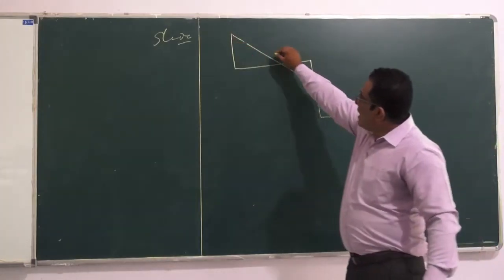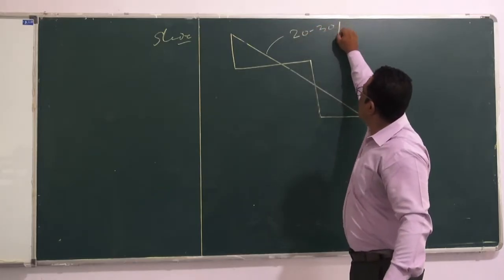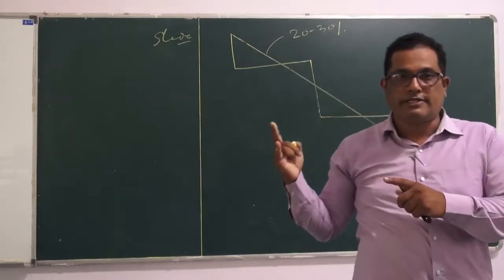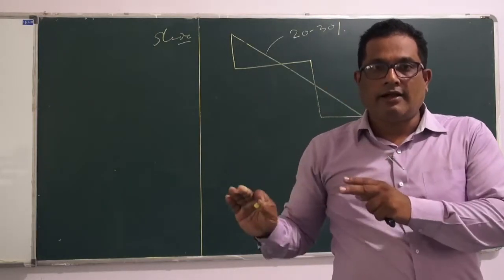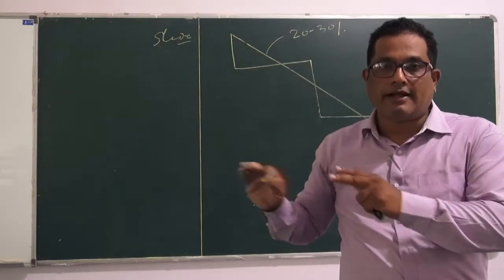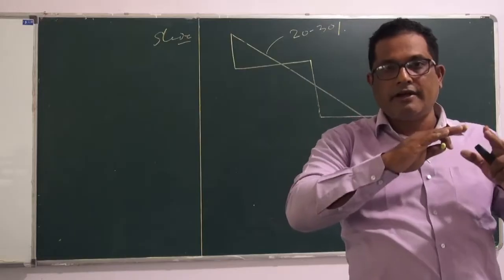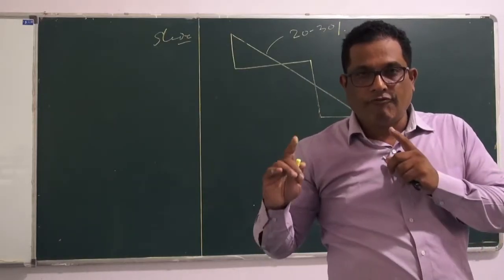So bench terraces are for land with generally more than 20 to 30% slope. Broad-based terraces are constructed on flatter land, and not the entire land is cut or filled, but it is divided into a series of mildly sloping ridges and furrows.